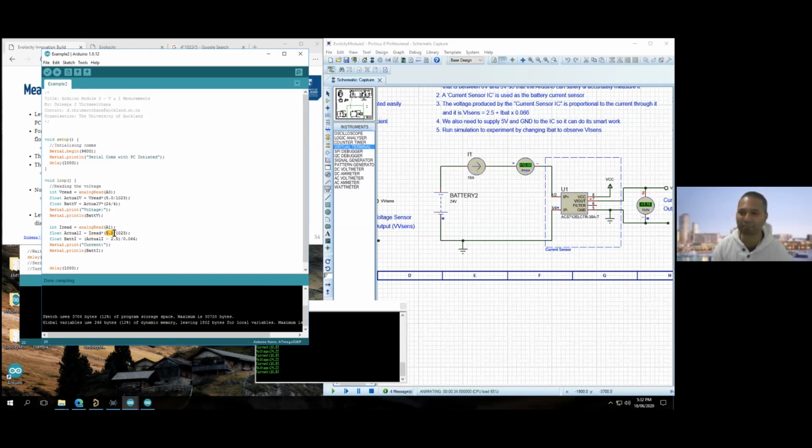It has to have that .0. Okay, so I need to initialize a float, then use the float. If you use this as a float, then that's fine. Otherwise, you need to tell the Arduino program that it needs to be a float when you do the calculation. In programming, this is called type casting.